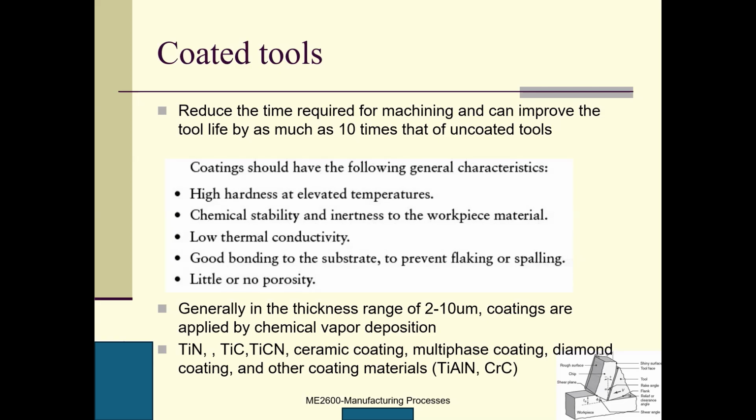The coatings should have the following general characteristics. First one, high hardness at elevated temperature. This is very, very important. Otherwise, if the temperature goes up and the hardness of the coating material is low, it will be worn out very quickly.